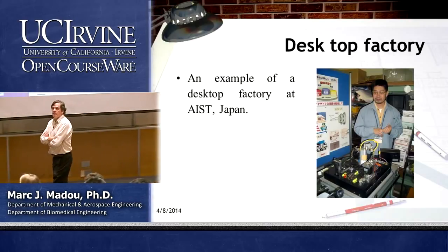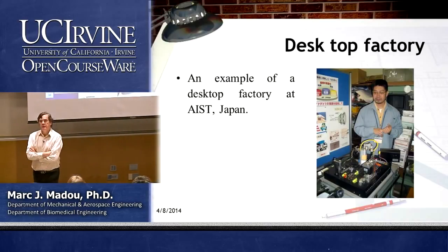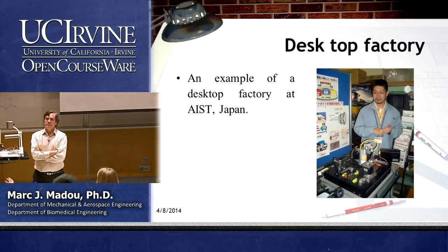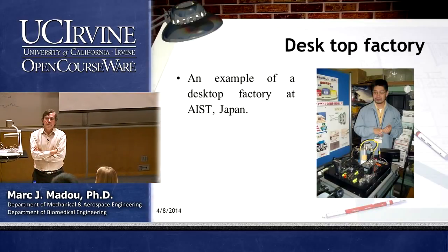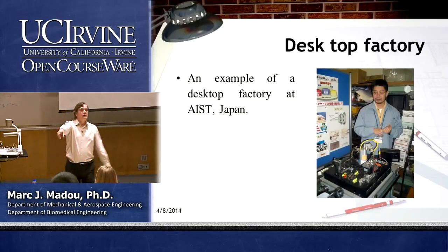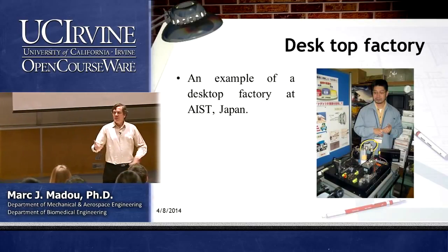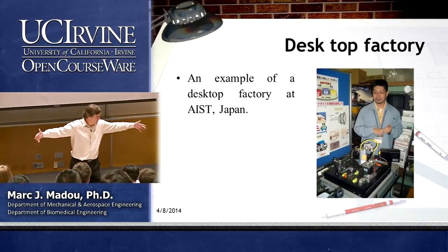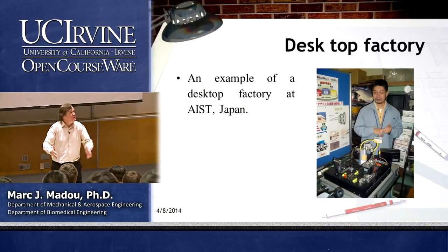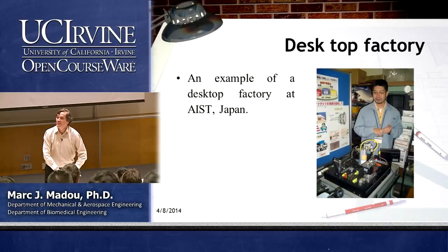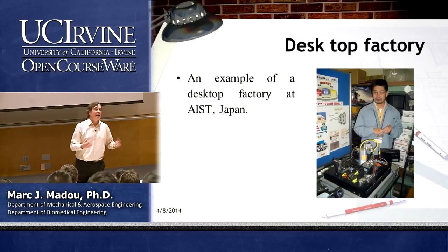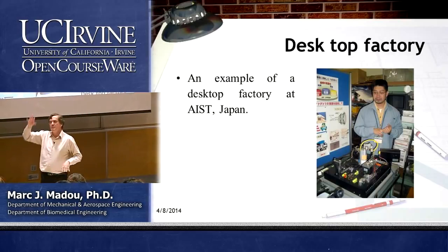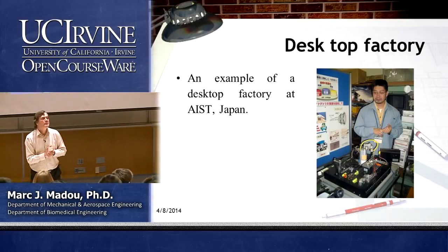By reducing the weight of the tool itself, by reducing the weight of the micromachining machine, are we also reducing the relative tolerance that a machine can have? Yeah, that's a very good point, right? He's talking about that weight ratio. If you make that very small thing, why would you have a machine of a ton? You cannot make the machine too small because it would become sensitive to vibration and therefore would become less accurate. So that's why people have studied that. They make kind of an optimum ratio for that.